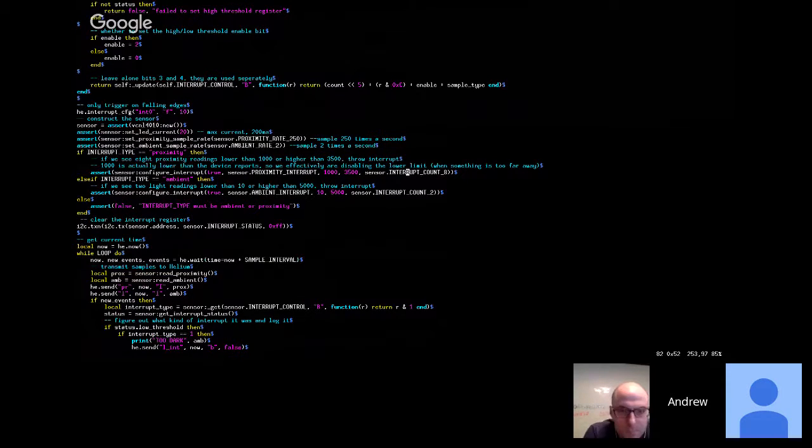And then I told it I have to see eight values above 3,500 or below 1,000 before it throws an interrupt. So you can actually kind of smooth out your signal. If you just see one reading that's high, and you want to know that it's been high for 8. Remember, it's sampling 250 times a second. So 8 is pretty quick, but at least it smooths out your signal for you.